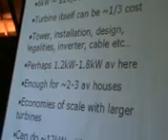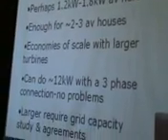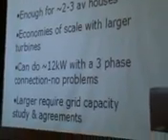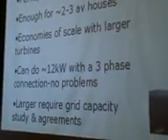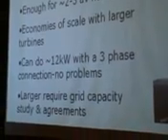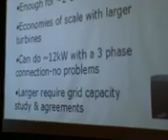In terms of practicality, you're allowed to connect up to about 12 kilowatts with a 3-phase connection on site without any issues. You don't need to contact the electricity company or anything. If you did ever think of a bigger turbine, you'd need to look into that a bit more carefully. So that gives you an idea. It's a green light for something smaller than 12 kilowatts; it's pretty straightforward.